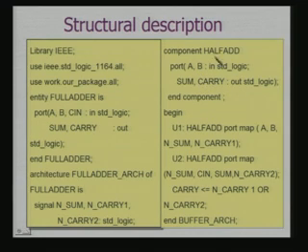So, it gives you the description of this full adder in terms of components, and then the actual architecture, this is the definition part, architecture is U1 consisting of U1 and U2, which does a port map, okay, fine, and it is now defining the carry. So, this is completely defining my full adder as a connectivity between the two half adders.